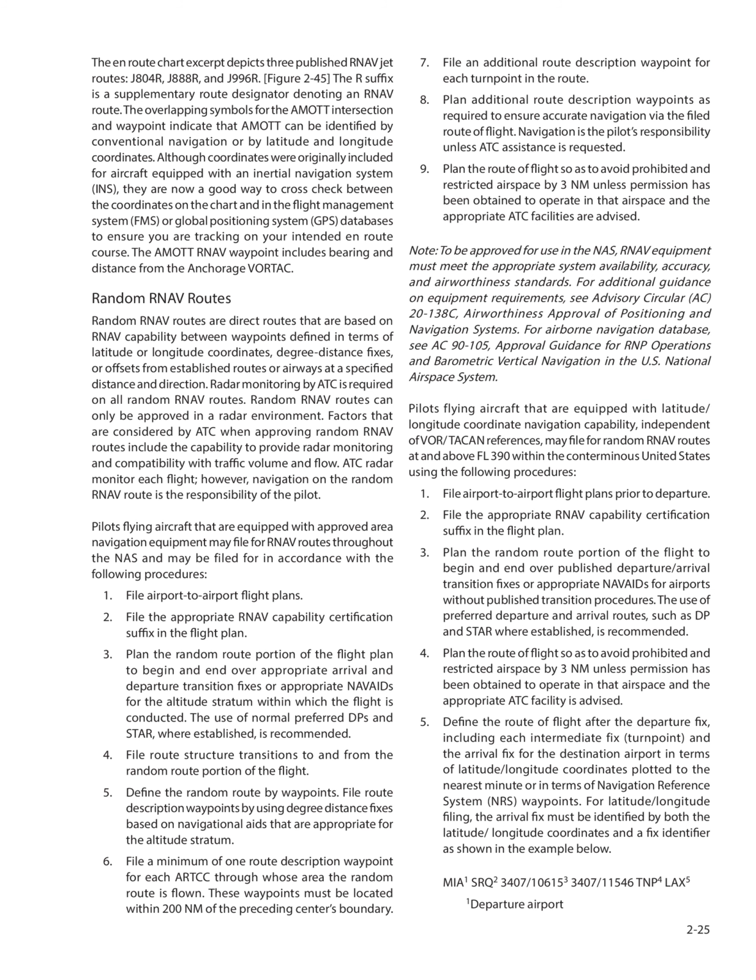Plan the route of flight so as to avoid prohibited and restricted airspace by 3 nautical miles unless permission has been obtained to operate in that airspace and the appropriate ATC facility is advised.